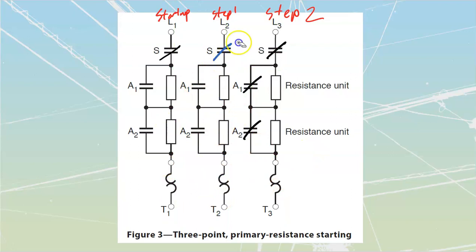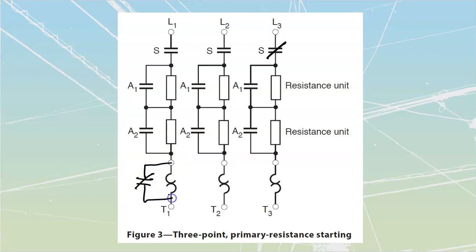I'll just erase this over here so we can see them, but we can see that we have these ones over here. If I did need to go and shunt these ones out, what I would do is operate off of my A2 and my A1, and all I would need to do is bypass these ones with a normally closed set of contacts that is going to be attached to my A2. And that would allow me to divert current around the overloads. The overloads do have a small amount of resistance. That's how they generate heat.